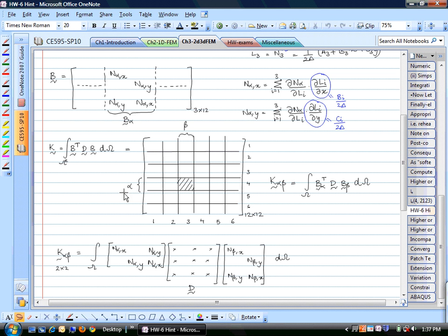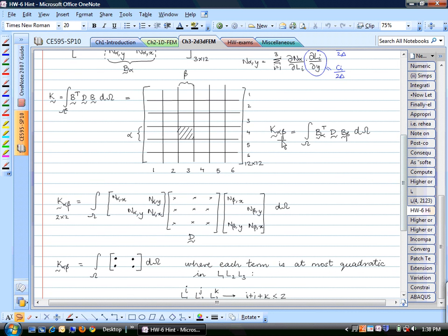So that's essentially a loop over alpha and beta. So what we are trying to do is calculate this small circle or this small square portion of this entire matrix. So after that double nested for loop is done, you will have this entire matrix. So what we've done now is converted the problem from this 12 cross 12 matrix to a small 2 cross 2 matrix. And we know how to calculate that small 2 cross 2 matrix, this k alpha beta. This is the small portion k alpha beta.